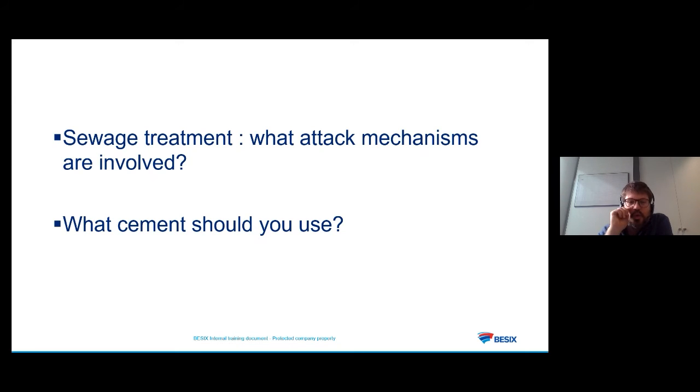And the carbonation, you can also work on it by increasing the cover of the concrete on the rebar. You can also put some painting or protection on the concrete to avoid the CO2 penetrating too fast. And then the best solution is self-healing concrete, of course, because actually the cracks are the worst for the corrosion of the rebar. So I'm sure that in a few years we will use only self-healing concrete, so there won't be any problems then. I hope this answers your question. Yes, definitely. I did want to know what they do practically, so it was a good answer.